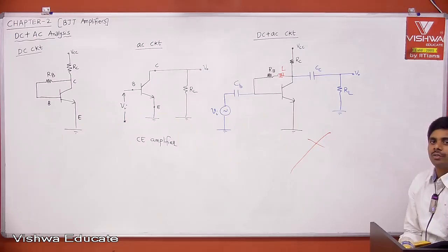It is not straightforward, right? We studied so many circuits from AC analysis and different circuits in DC analysis. Then finally we got the RC coupled CE amplifier, which is what gives you Q point stability and keeps the transistor in the active region, which is nothing but biasing, and finally the common emitter configuration, which is going to give you more power gain. Okay. Therefore, the ultimate amplifier is nothing but the RC coupled CE amplifier.